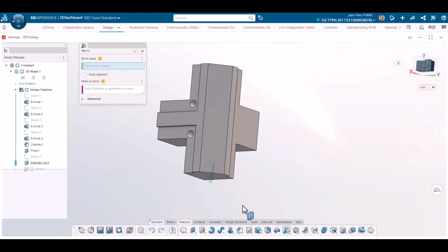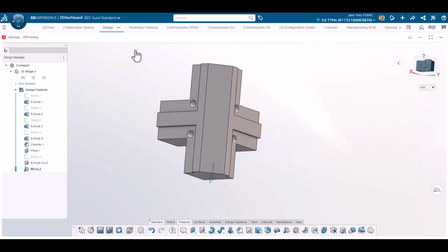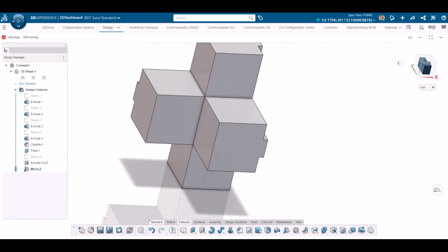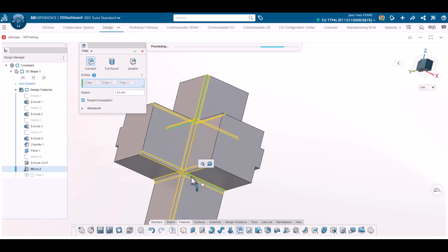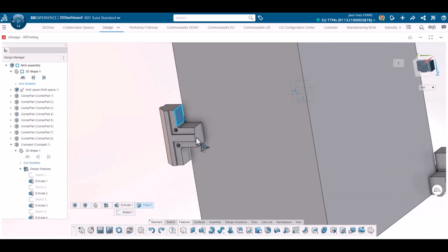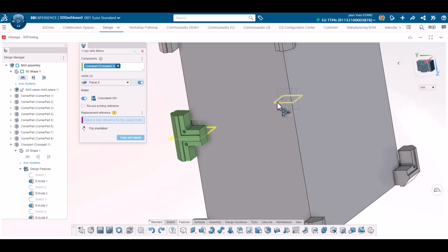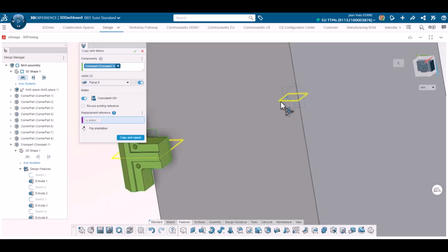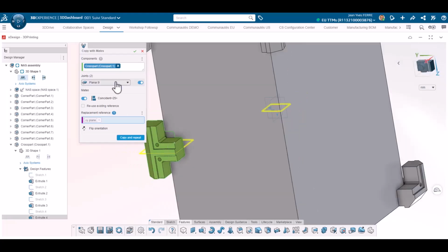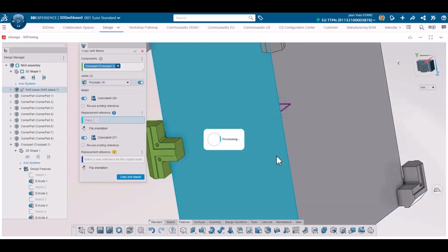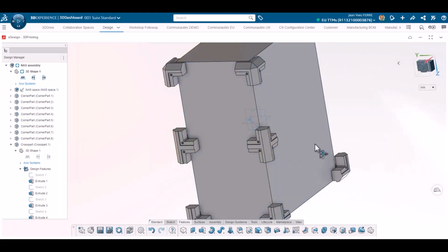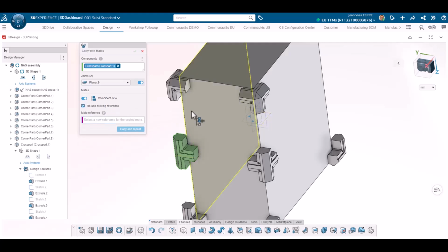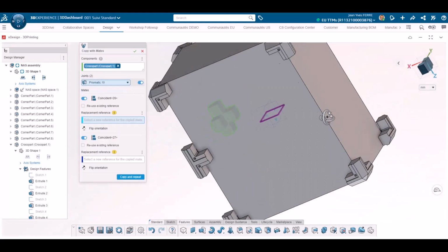Of course, there will be smaller parts on front and back side, and these parts will have same sketch dimensions to keep unity in the design. I finish with a fillet, leveraging edge order to go faster. Then again, I mate cross part with my extrusion. Here I leverage the symmetry of my model. This will ease mating operations, and of course I also use copy with mates to expedite positioning of other crosses. For that step, I just need to select references used for mates of the seed part in the same order but for the new position.